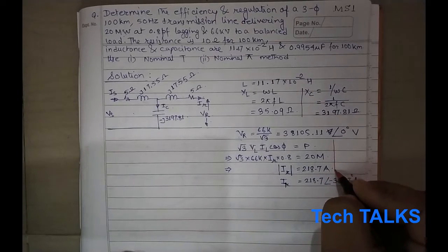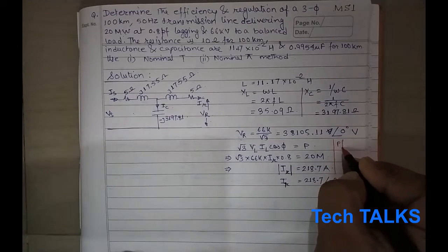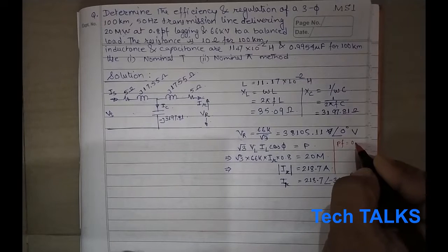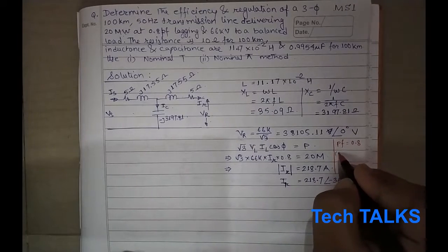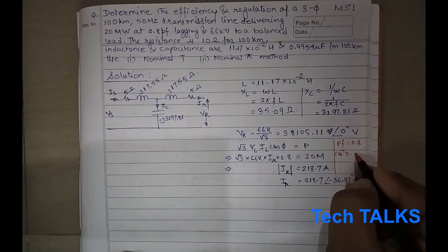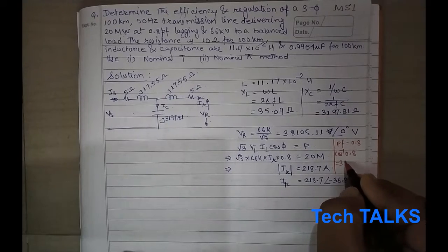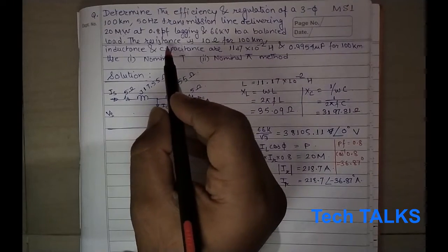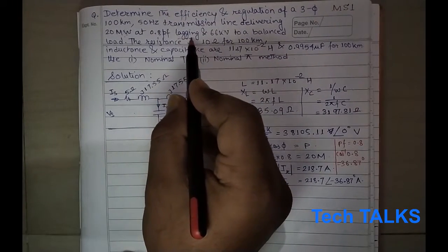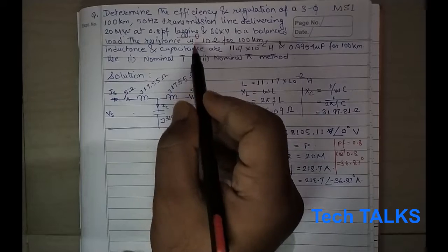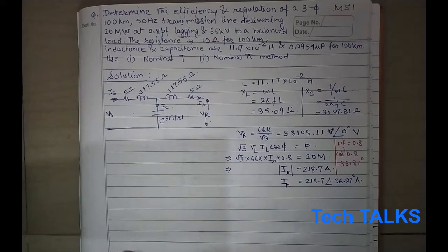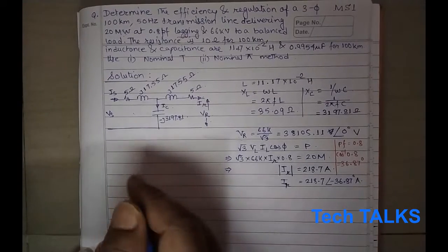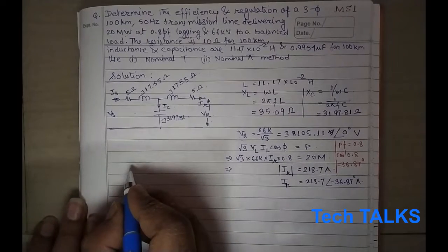that I am showing you, the power factor is 0.8, so cos inverse of 0.8 is equal to 36.87 degree. And here is another term, you see, lagging. So this lagging means that the current is lagging the voltage. Now we will draw the phasor diagram of whatever we have done.